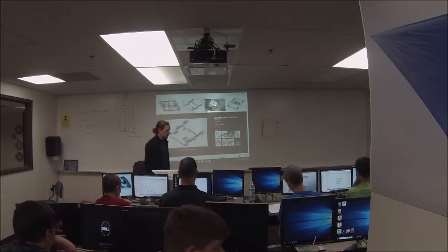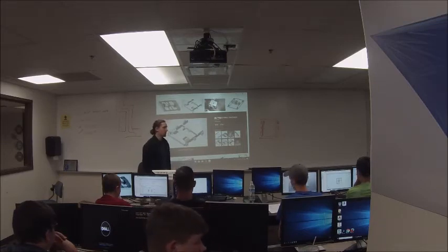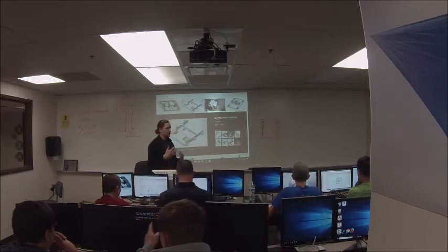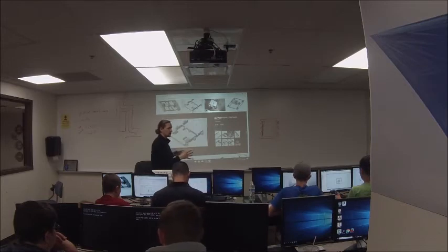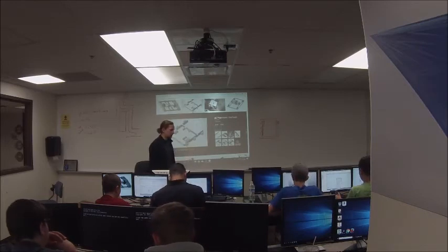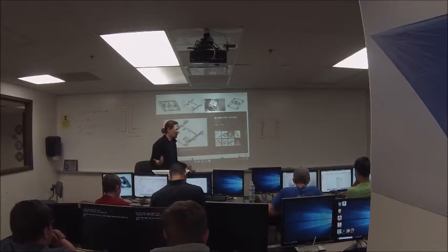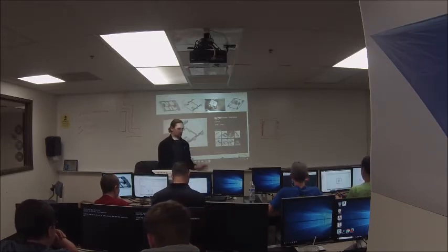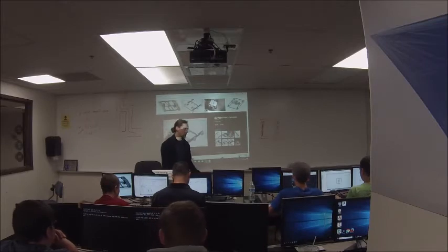So H drive is probably one of the simplest holonomic drives that's smooth. H drive is very, very smooth. With Mecanum, it's very sticky, so it's not very smooth. But H drive is very smooth, but it doesn't have any traction, right? Because there's always some direction that you can just push the drivetrain freely, give or take a little bit. They're terrible for traction, but they're very, very maneuverable, and they're not that complicated to build.